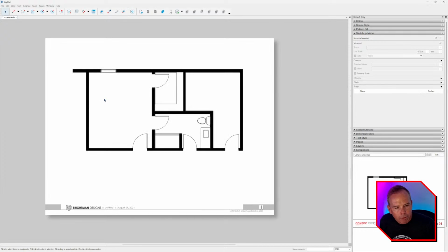By opening the SketchUp model from Layout, I don't have to go to File, Document Setup, References, and then reload the reference. And by using that auto render, I don't have to right-click render or use a keyboard shortcut ever. So this is the way to work, I'm telling you.